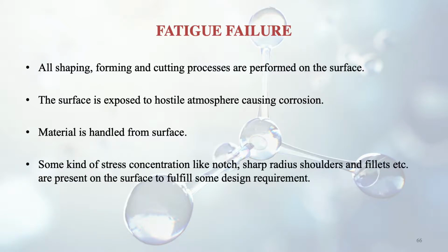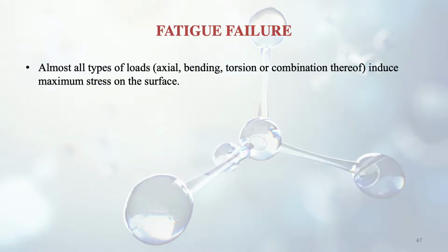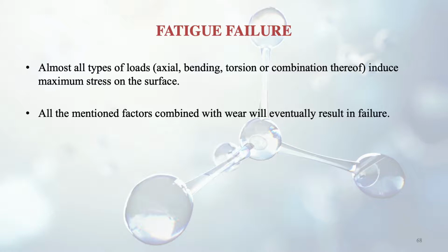Some kind of stress concentration like notches, sharp edges, shoulders and fillets etc. are present on the surface itself to fulfill some design requirement. Almost all types of loads, whether axial, bending, torsion or a combination of them, induce maximum stress on the surface. So all these are the factors which combined with wear will eventually result in failure. So fatigue combined with wear will result in speedy failure actually.